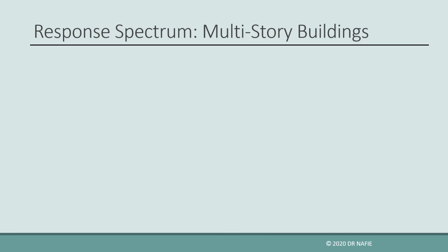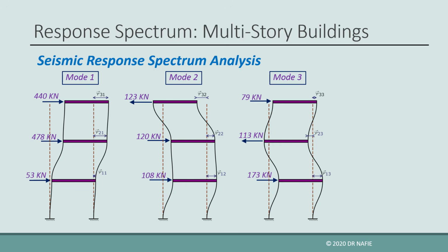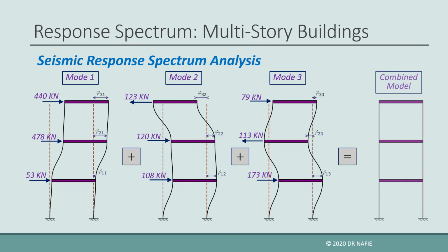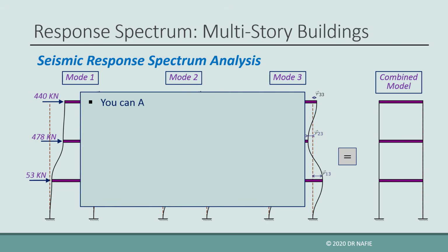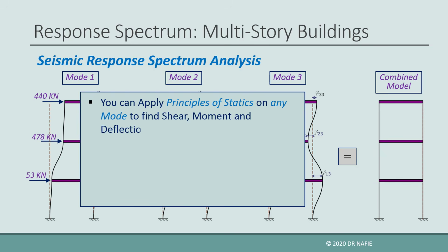Now that we have obtained the spectral seismic forces for each mode, we need to combine these modal forces using an acceptable method, such as the SRSS method. However, we need to point out some important issues regarding this process. For each mode, we can apply the principle of statics and the equilibrium equations on the modal forces to obtain any straining action or displacement in the building.